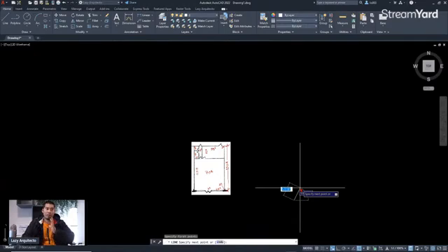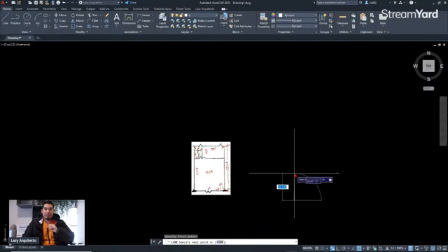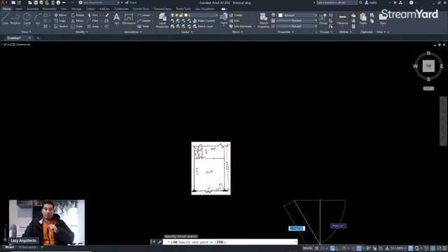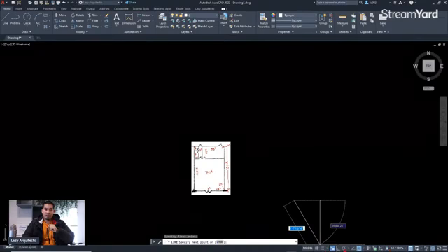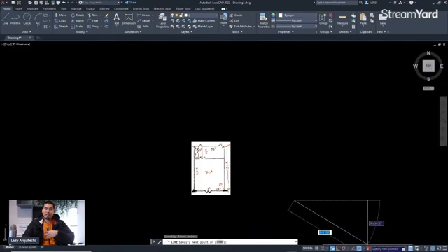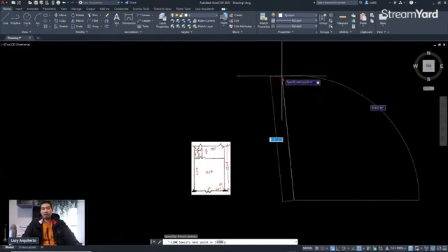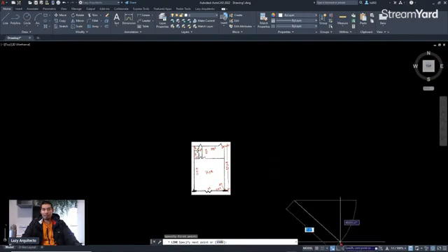So you saw that I want to draw this line nicely and straight. AutoCAD gives us these options on the status bar to check and uncheck the precision settings that we need. In order to draw my line straight, I need to activate this option on the status bar, which is the ortho mode.